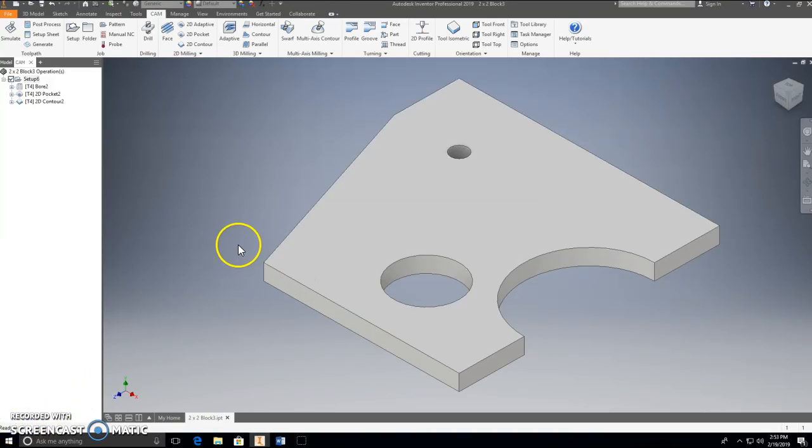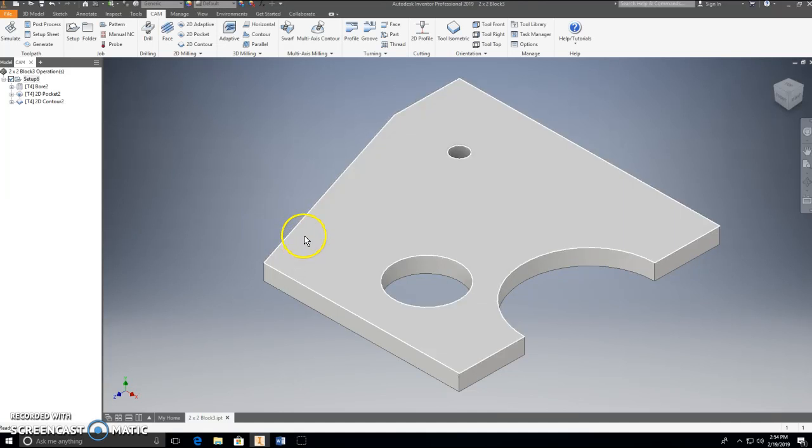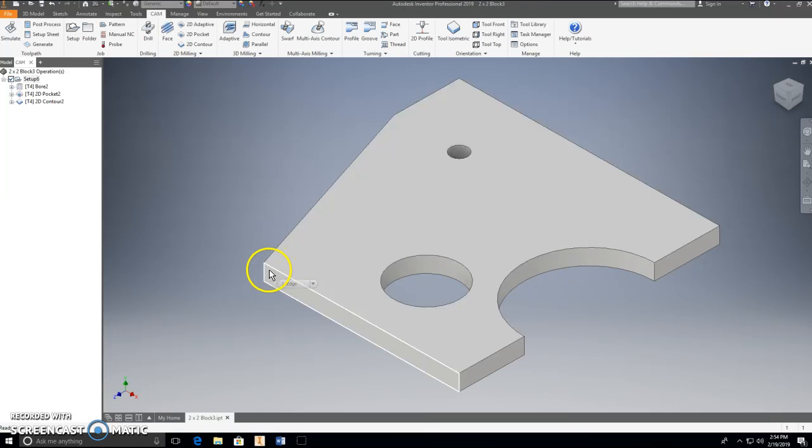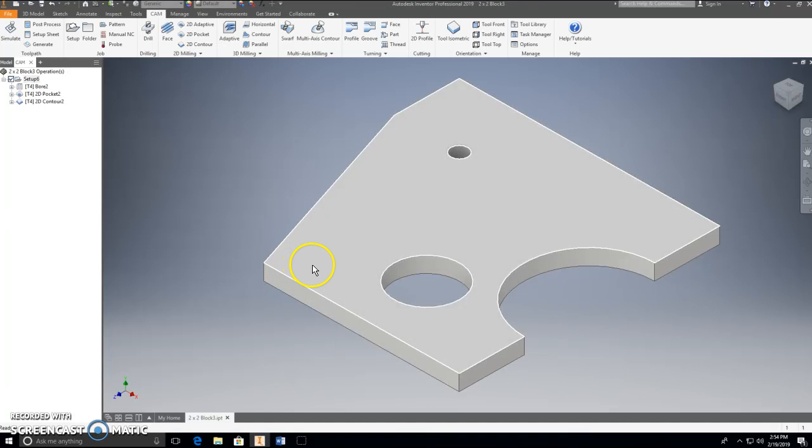To measure your material, you're going to have to get a caliper. So you're going to take your caliper. I have 3 different thicknesses of material I'm going to have you pick from. You're going to measure that material, and whatever measurement you come up with, you're going to set the thickness of your material to that. So let's say you pick your material, and it measures 0.215 inches. You're going to set your thickness of your material to 0.215 inches.